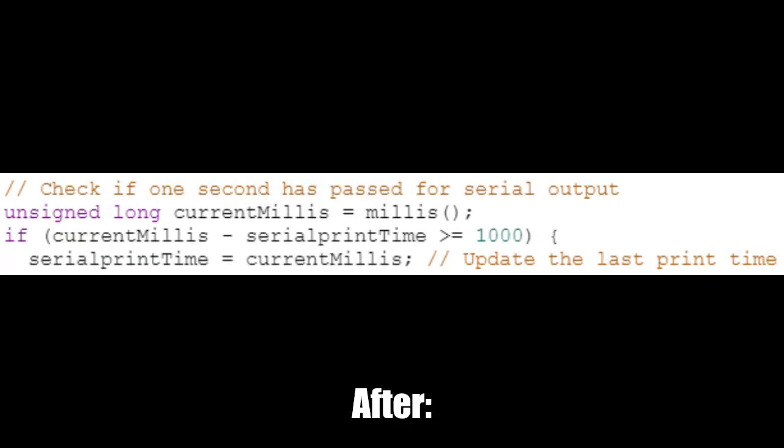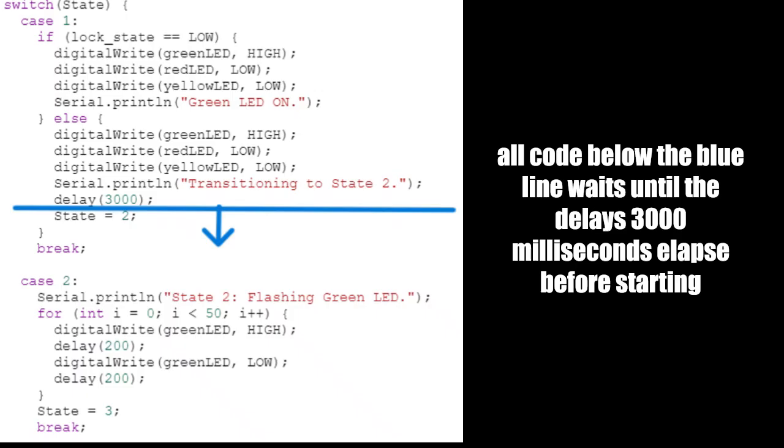The improvements between A1 and A2 are plentiful. Firstly, the implementation of millis as compared to delay has reduced the length of our code and improved its legibility. Also, the fact that millis are non-blocking functions means that we can easily integrate tasks that require inputs at varying intervals, such as our LEDs, and allows the function to iterate much faster by preventing blocking, which is when code stops until the timer on the delay function is finished before moving on to the next line.